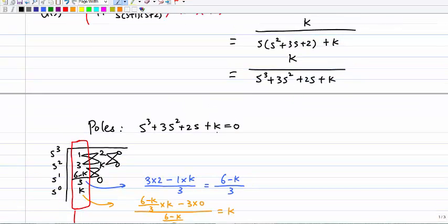Now of course here I have some parameter K. So I follow the same procedure I mentioned before. First I build a Routh array. I use a horizontal and vertical line, and on the left-hand side of the horizontal line, I put s cubed, the highest power I have, then s squared, reduced by 1, s1, s0. Then the coefficients are 1, 3, and 2, and K. So I put here 1, 3, 2, and K. Of course, I put 0, 0, since I need it later on.